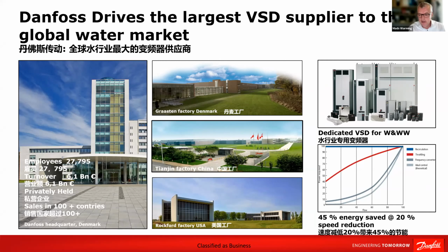The reason that controllability is so important is that the water industry is different from more or less all industries: the load on the facilities jumps up and down during 24 hours, down to 10-20% during nighttime and at peak in the morning and the afternoon. Therefore it means so much whether you have the capability to regulate or not.